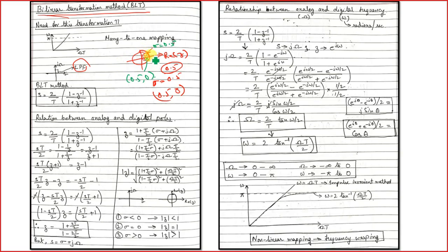So when we use the impulse invariant method, our poles are being restricted within a very small area, and because of this it becomes difficult to design other types of filters like the high pass filter, because in our previous classes we have seen that for high pass filters we need to put some poles at the higher frequency region, near pi, right?